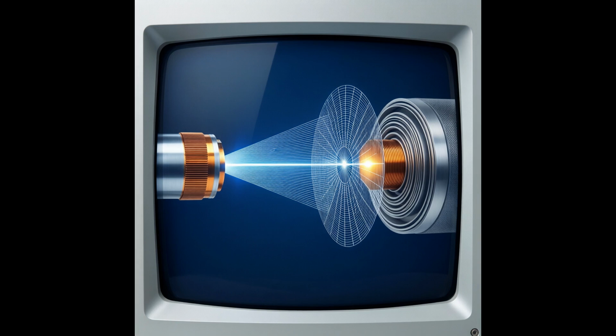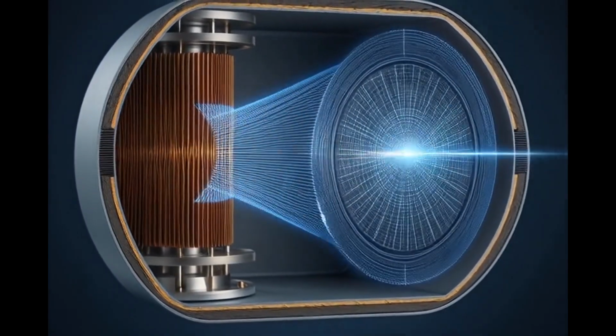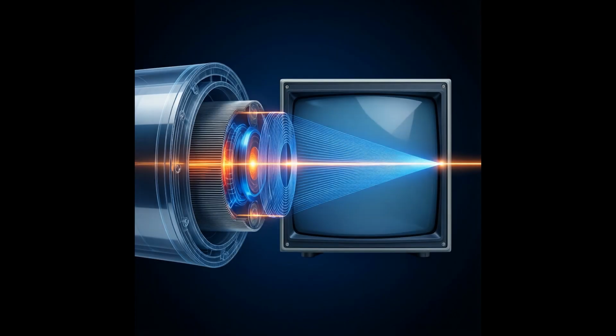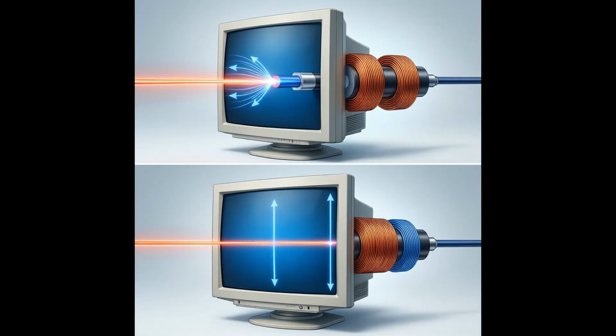However, a fast beam is useless if it spreads out and hits the glass randomly rather than forming a sharp spot. To solve this, we use electrostatic lenses formed by grids held at specific voltages relative to the main anode. These grids create curved electric field lines that act like optical lenses for light, bending the electron paths inward toward a central axis. As the electrons pass through these focusing fields, their trajectories converge until they meet at a single precise point on the phosphor coating. Without this convergence, the image would appear as a blurry wash of color instead of distinct pixels or lines.